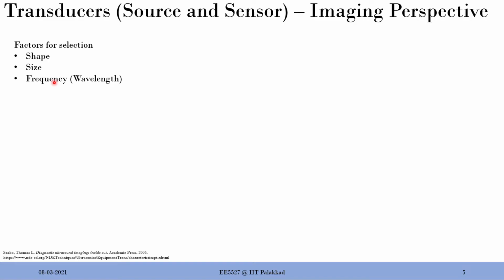with. You of course have another factor, which I didn't mention here, which is the amplitude, but the amplitude is mostly controlled by your electronics, but the frequency is controlled by the transducer that you choose, the antenna that you choose. The moment you design the antenna or the transducer and you finalize that, there is no way you will change the frequency.